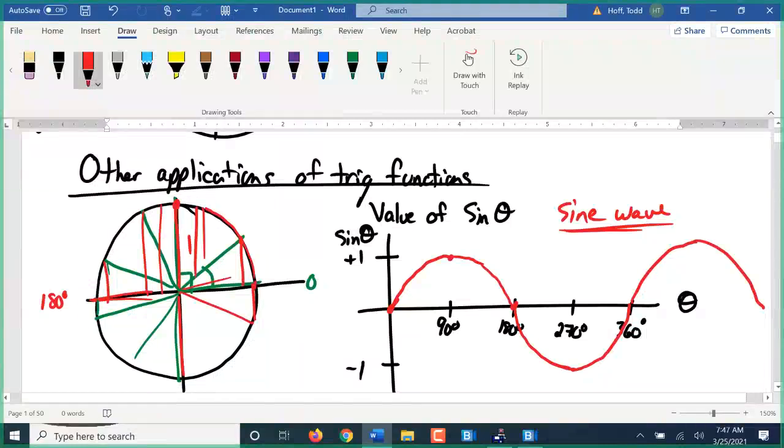It's actually, for a 110 volt outlet, from a positive 170 volts to a negative 170 volts. The voltage follows that cyclical wave, and that's what allows the motor to turn. It goes from positive as the motor makes its first half turn, then it goes to negative as it makes the second half turn to reverse polarity to keep it running.